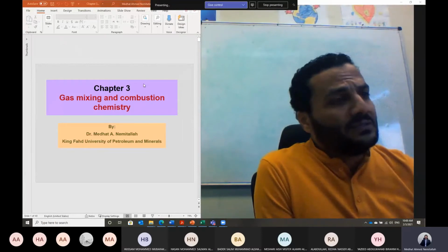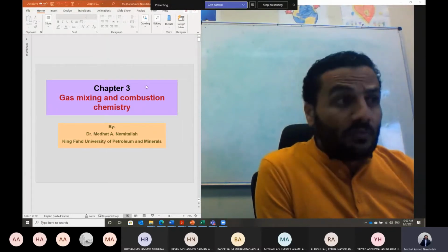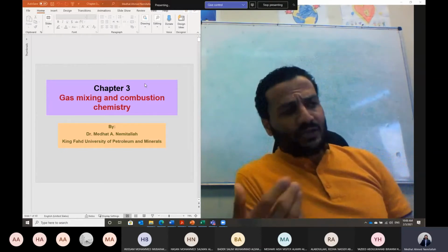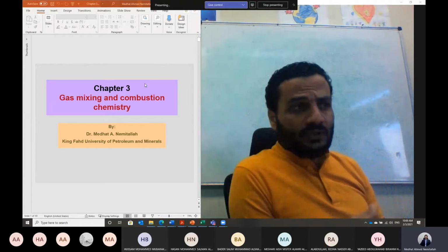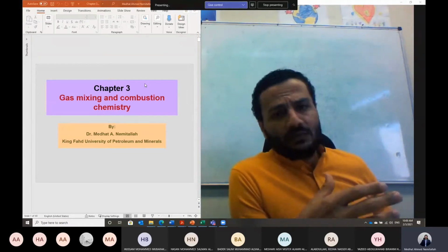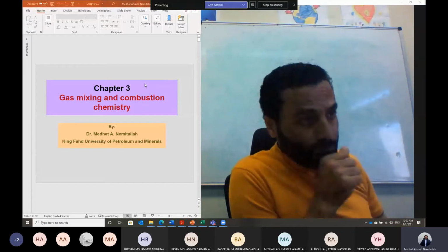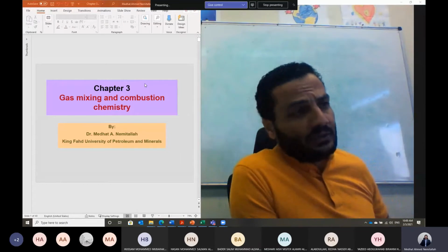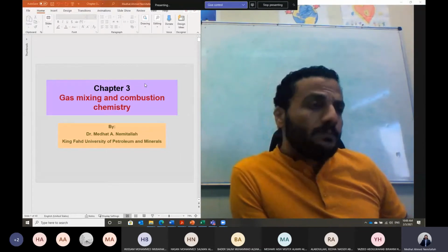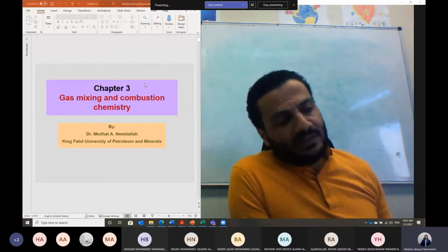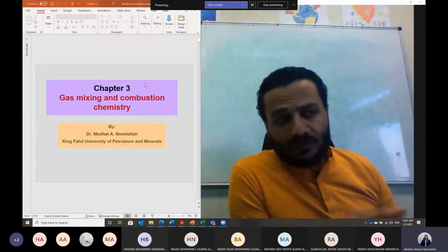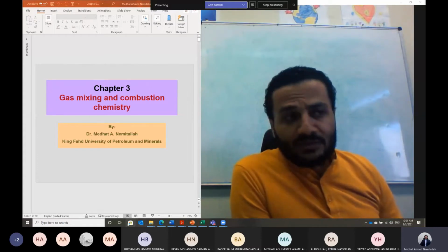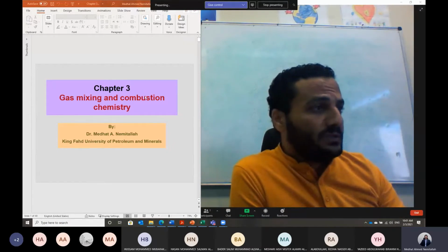Inshallah, today we'll be starting the part related to the chemistry or the combustion chemistry. Today we'll be starting with the gas mixing, mole fraction, mass fraction, how to calculate the molecular weight of a gas mixture, the gas constant, specific heat for a gas mixture, and how to calculate the other properties also for the gas mixture, like internal energy, enthalpy, the entropy. I think all of this actually you have heard about, and I think actually you know about it. But I just have to introduce it again here. So just a kind of refreshment, because we will need it actually in this chapter.